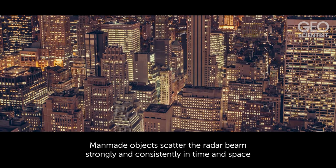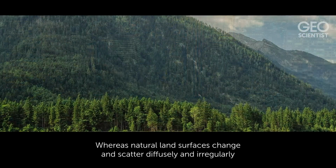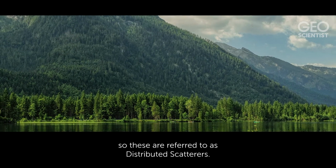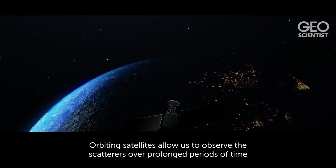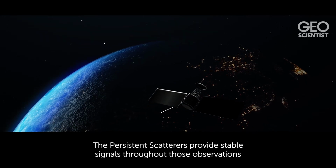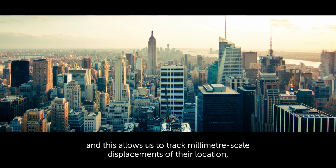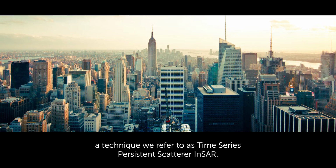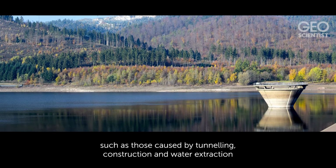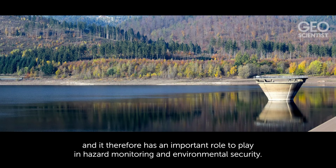Man-made objects scatter the radar beam strongly and consistently in time and space, and we call these point or persistent scatterers, whereas natural land surfaces change and scatter diffusely and irregularly, so these are referred to as distributed scatterers. Orbiting satellites allow us to observe the scatterers over prolonged periods of time by combining many SAR observations. The persistent scatterers provide stable signals throughout those observations, and this allows us to track millimetre-scale displacements of their location, a technique we refer to as time series persistent scatterer InSAR. InSAR therefore allows us to precisely measure small ground motions, such as those caused by tunnelling, construction and water extraction, and it therefore has an important role to play in hazard monitoring and environmental security.